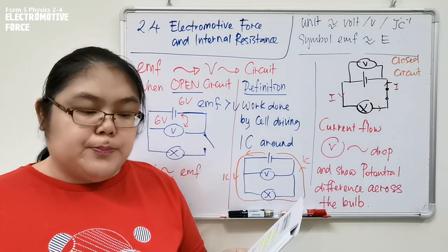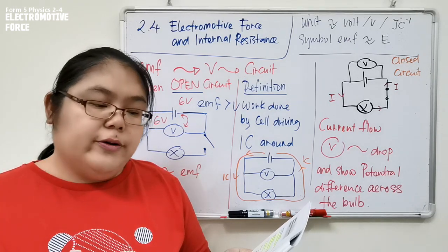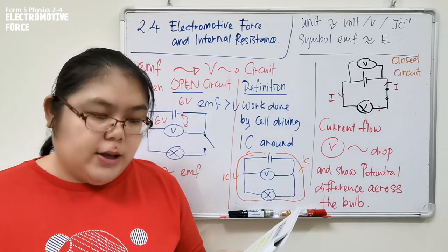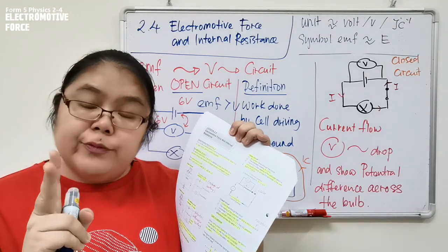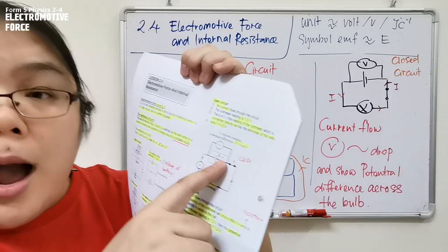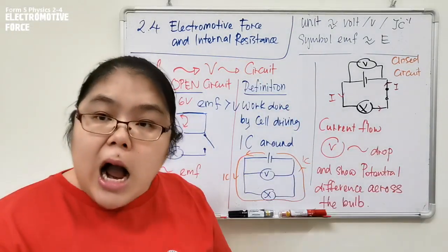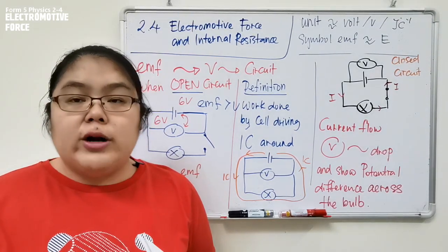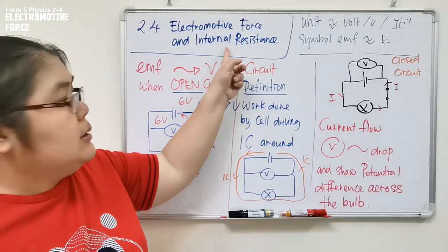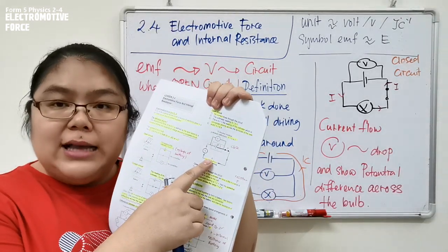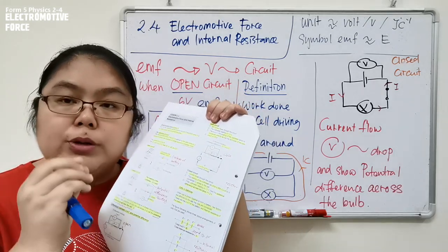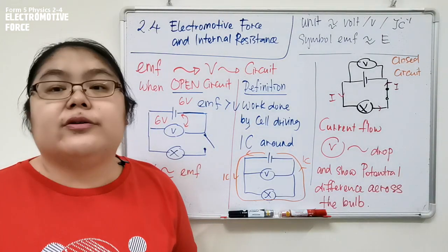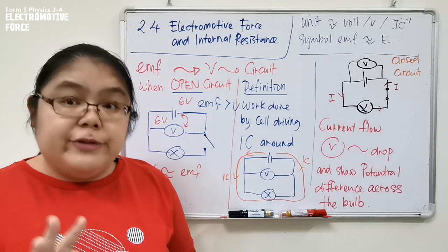Now your voltmeter is parallel with the battery. So from here, when you close the circuit, the current starts to flow through the whole circuit. Now we have two resistors when you close the circuit, agree? One is a small r, another one is a capital R. So from here, I want to introduce a name first. Smaller r, we call it internal resistance. Outside, the R, for example where you put the bulb or a normal resistor, we put capital R. This one we call the external resistor. So we differentiate first.